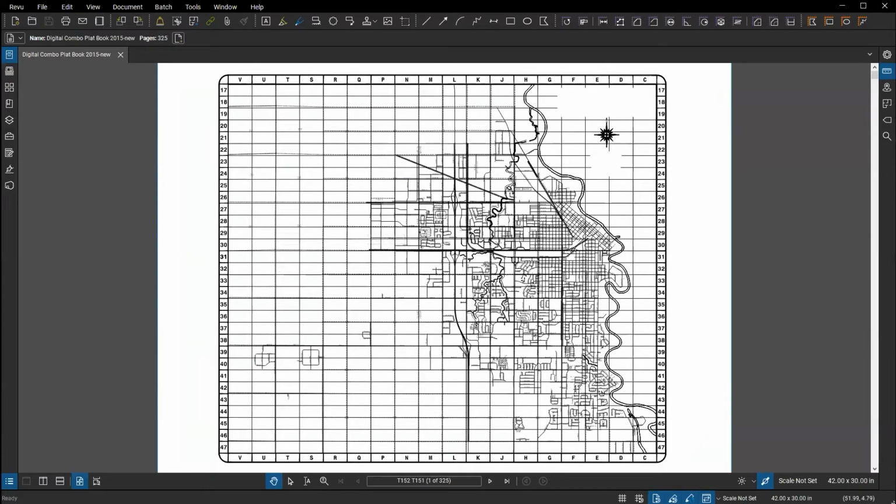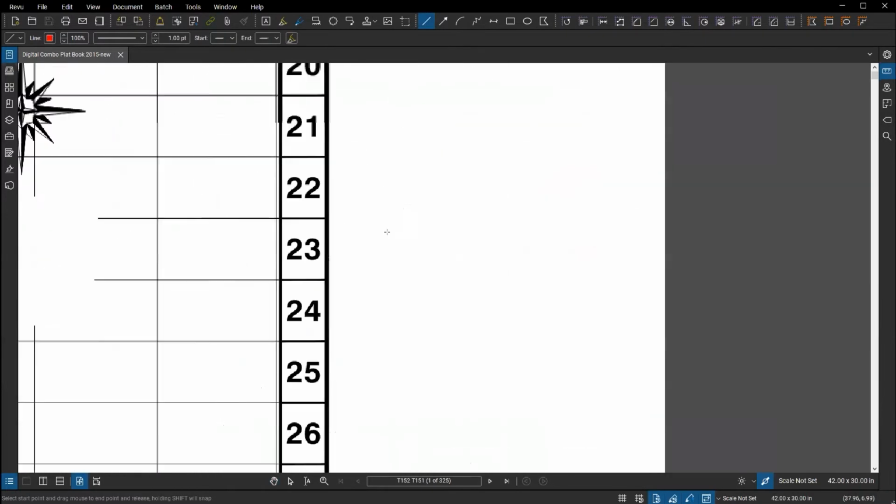So some quick tips on various tools that you may use. Again, some of these functions you may already know of, but just to give you some awareness of the various tools that are inside of here. Simple ones like the basic line command. So when you're drawing the line, you want to have this be horizontal. Just hold down Shift. We'll lock that in to be horizontal.